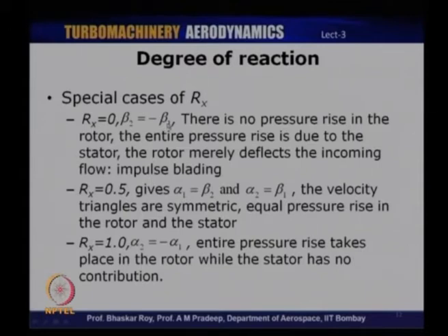When degree of reaction is 0, it basically means that there is no change or there is no contribution of the rotor to the overall pressure rise, because degree of reaction tells us what is the contribution of rotor to the overall pressure rise. So, when degree of reaction is 0,